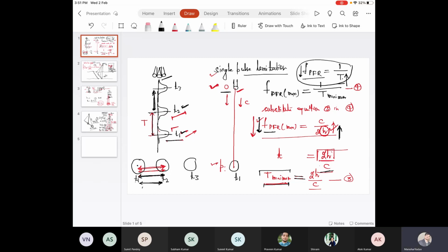When this gap increases, data density will decrease. In one line, fewer points are hitting the ground. So if data density decreases, the quality of data will decrease. You can't get a dense point cloud, so you can't geometrically represent that object.